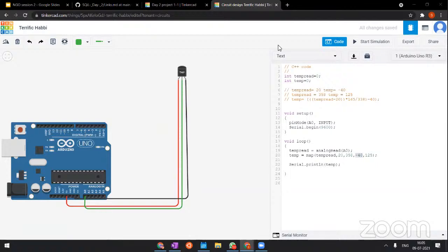Yeah, it's A0, not AO. Azim, in the pin mode, inside the void setup, the first statement, it's pin mode A0, not AO. And the rest of your code. And the temp read also, inside the void loop, the first statement, put A0 instead of AO. Other than that, I think your code seems fine. Just try that and it should work.